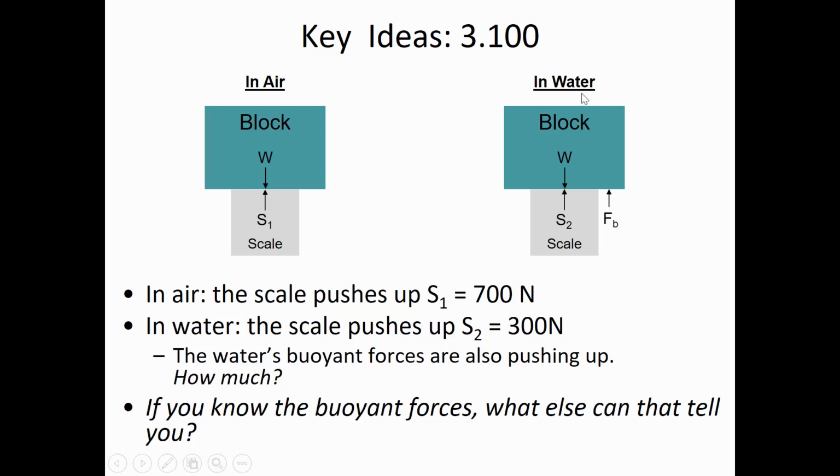But now when it's measuring that same block in water, then the scale is pushing up with 300 newtons. And so you can, from that difference, determine what the buoyant forces are. And if you know the buoyant forces, then that can tell you things like the submerged volume. So if you need to reflect back on both of these hints, of course, they're going to be in the video that's posted on YouTube. But I thought both of those could deserve a picture, so I thought I'd provide it.